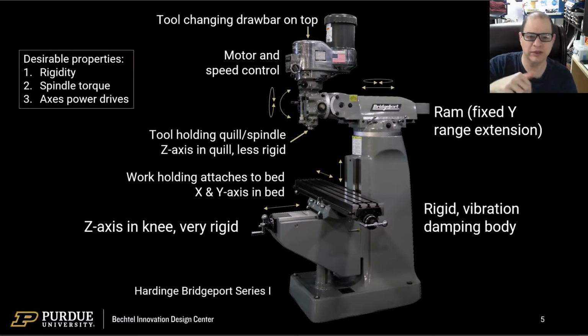If we drive a tool into something and the machine itself flexes, twists, or distorts, then we're not going to get the result we want in the actual metal itself. You know, we're using this machine to imprint our will into a raw block of material. If the machine is weak, then our will isn't going to fully be expressible by the system. So rigidity is hugely important.